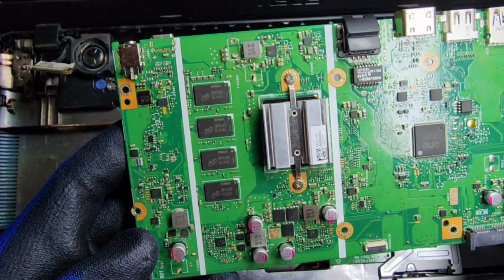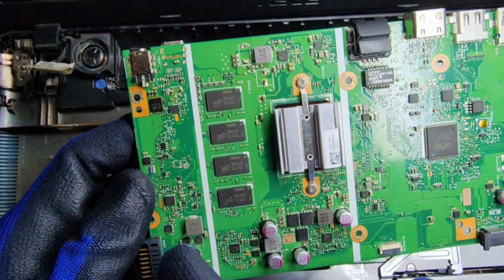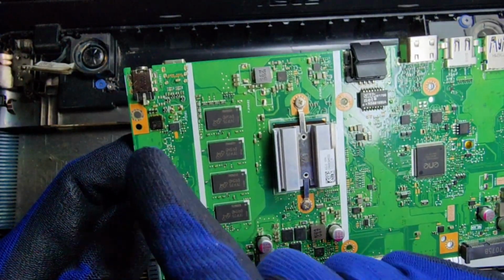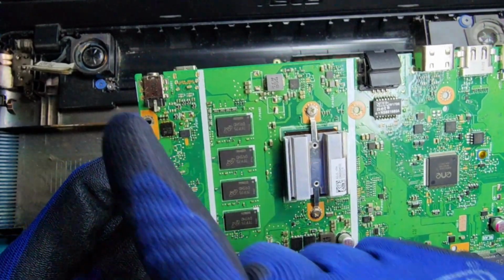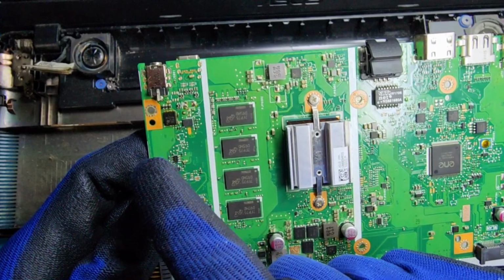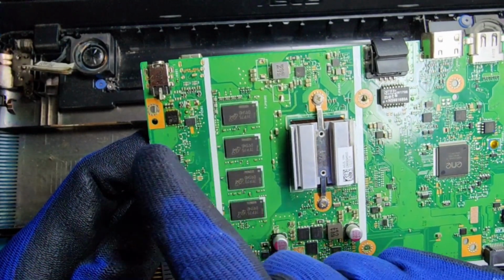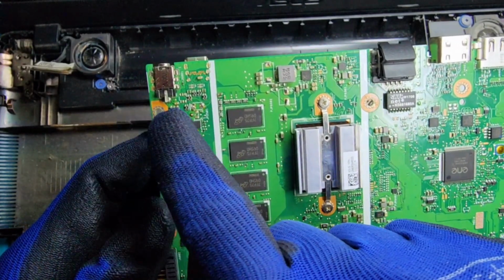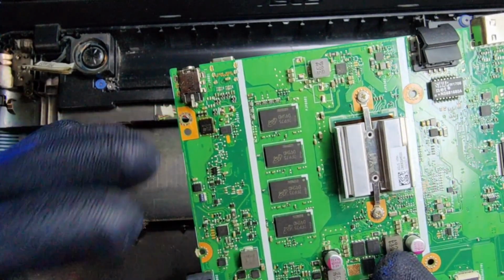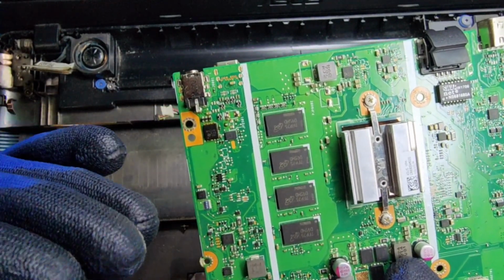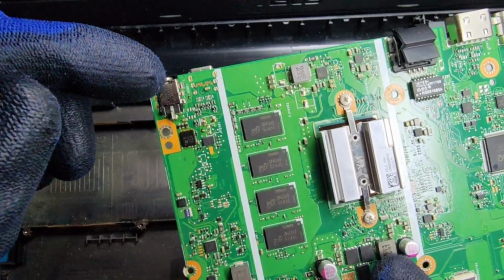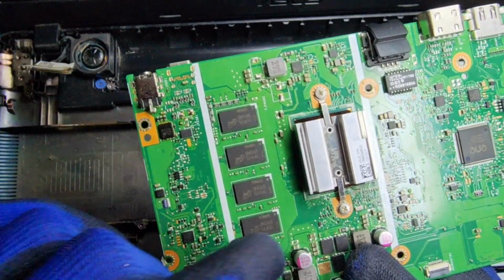Okay. And also I wanted to say another feature of the charger IC. Whenever you connect the adapter, the charger IC will not immediately turn on the main power rail. It will make some delay, around 50 milliseconds or 150 milliseconds. After some delay only, it will switch on the main power rail, which is called the soft start function. Soft start means once you connect the adapter, it will take some delay, and then only your adapter voltage will be transferred into the motherboard.